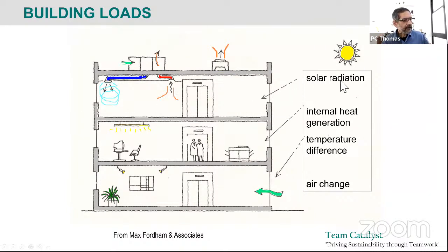So we talk about heat from solar radiation, or heat gain from solar, which comes through the windows. We talk about the heat that is generated by internal equipment. Mansi told us, I think if I remember right, she had 100 watts per desktop computer, 30 watts per laptop computer, etc. Okay, and there are two other things. There are equipment loads, there are lighting loads, and there is heat load from people, okay? So we need to account for those things.